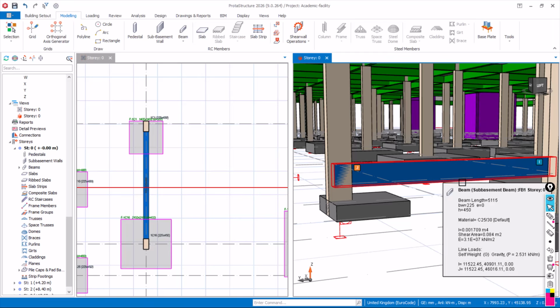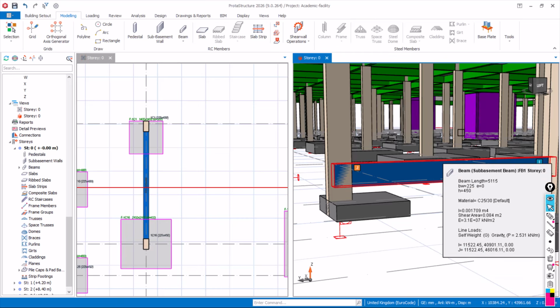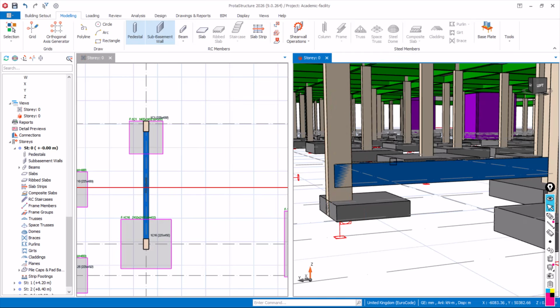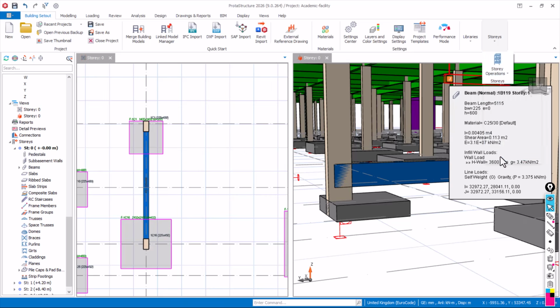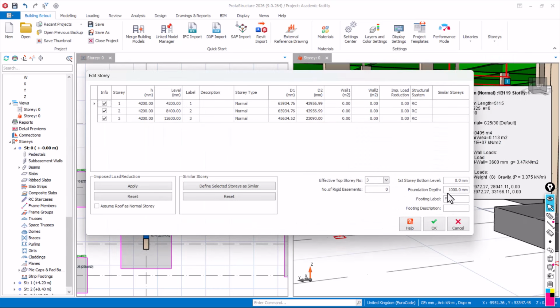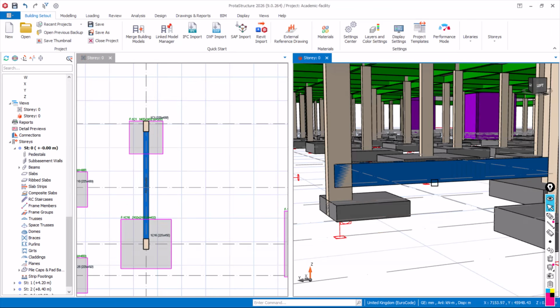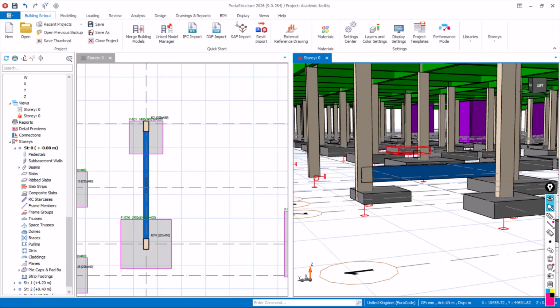The first thing to do is to locate and look at your foundation depth, which you have here in the foundation building height. You can see my foundation depth here is 1000, although this can change at site. This is just my assumption for this design. It always changes at site based on the topography of the land. So now that I know it is 1000, which all other footings here are generalized on.